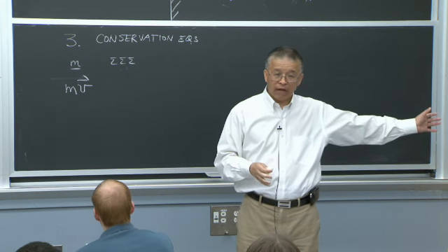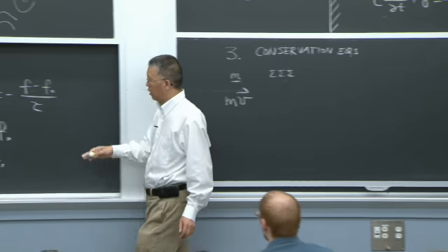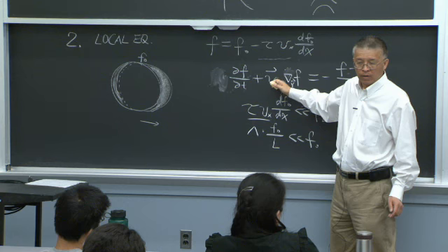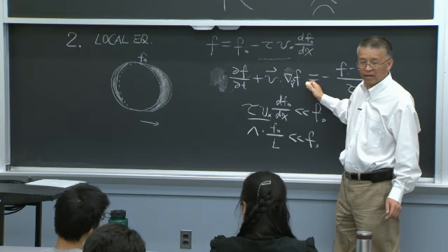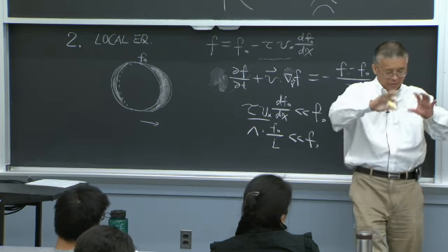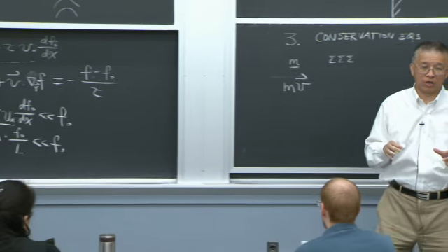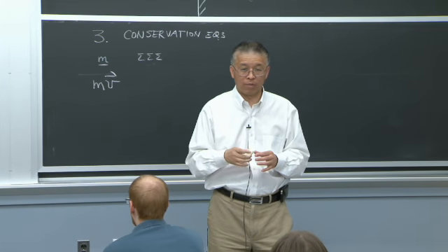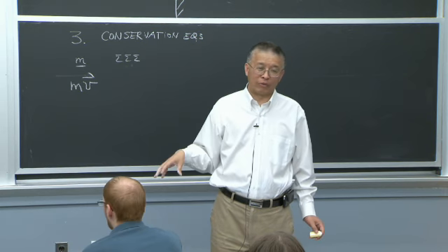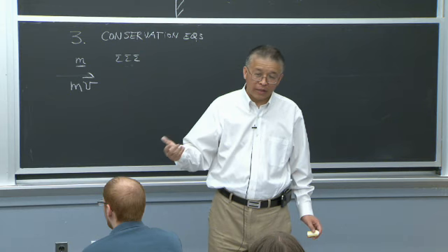On the left-hand side, you will have the convection term in the Navier-Stokes equation. On the right-hand side, you'll get the pressure and the Newton shear stress, the viscous term, right? But there you still have to put in the constitutive relation to get the Newton shear stress.